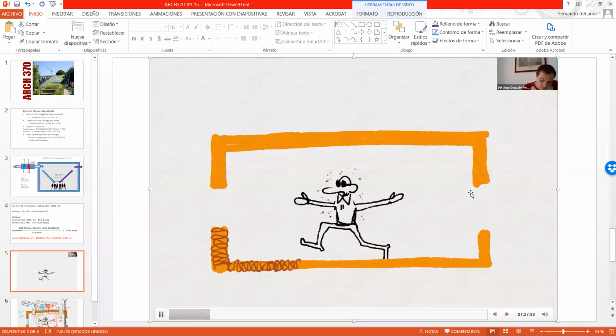In the floor, usually we have less thermal insulation, or the thickness of thermal insulation in floors is not as much as in walls and roofs, because we all know that heat tends to go up. So we have to protect the roof against the thermal losses, and the floor is not as relevant, but I like the idea of having thermal insulation also in the floor.